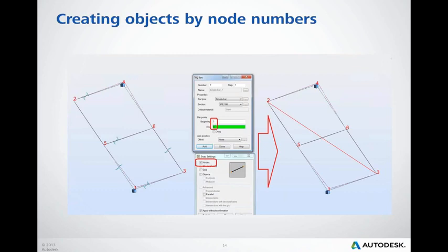Now some hints about modeling. If the snapping is set to nodes, the mouse cursor should precisely snap to nodes. Additionally, in such fields as marked in red on the bars window, it is possible to type bar numbers and node numbers to obtain the precise and desired effect.